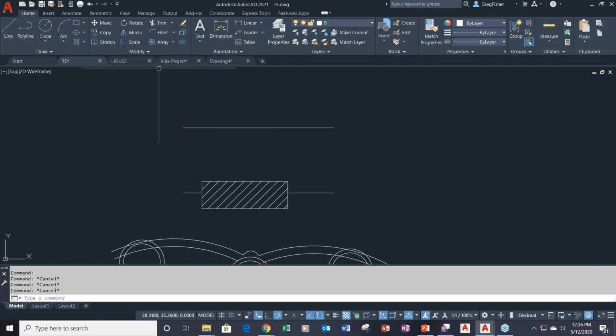Maybe I'm going too big there. Select it one more time, and then move my cursor over to here. Let me turn my object snap back off, type in the 30, and now it's that exact measurement. And that's the whole point of the break at point enhancement, is it's a lot more accurate. Before it was a lot of eyeballing.